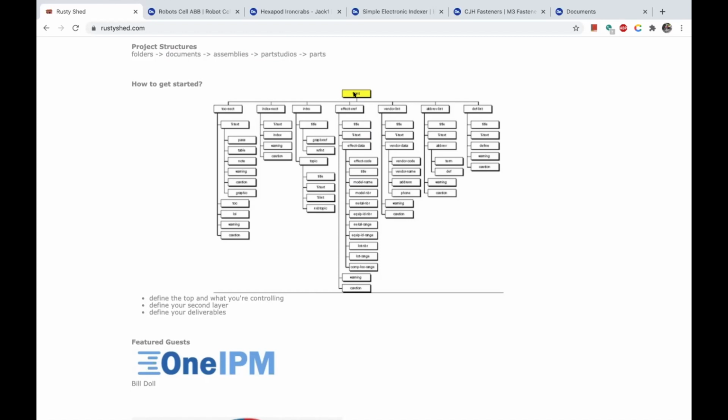And the first thing we did was, what's our top level assembly? There are 3 buildings. So we actually designed all 3 buildings and that was our top. Inside of the buildings, we actually broke it up into rooms and all of these were sub-assemblies. The cool thing of it is we had 6 engineers. None of them had to fix what the other people were doing. So this stuff will grow if you architect it and put it out.